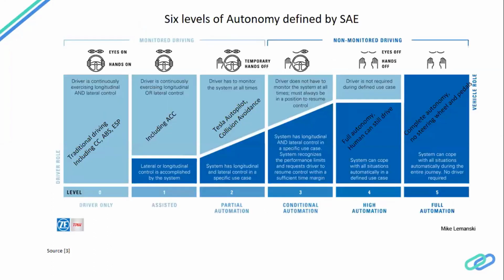And then there is one important race which almost all the companies involved in autonomous vehicles are running for, and that is the level of autonomy, which is defined by SAE as the way you are controlling your vehicle or the way it is able to control itself, basically the self-driving vehicle. So there are 6 stages of a self-driving vehicle. The first one, which is level 0, is a normal vehicle which has been in the market since the 70s or 80s, and involves only an anti-lock braking system or cruise control.